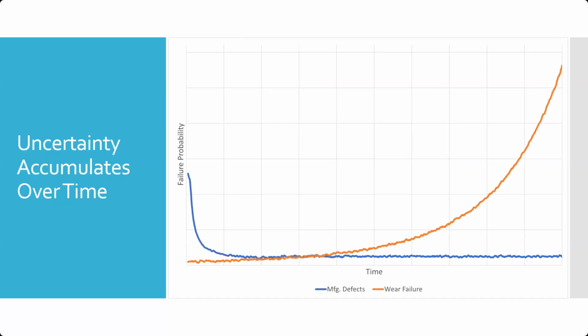The other thing we have is that once parts are put into service, they're going to wear over time. And so you'll have wear failure, and wear failure increases exponentially as you continue on the life of the part. The parts will eventually wear out, and that's usually fairly low for a majority of time. Oftentimes with wear failure, the curve is fairly flat until further over to the right side, but this one just happens to start to come up a little bit earlier.